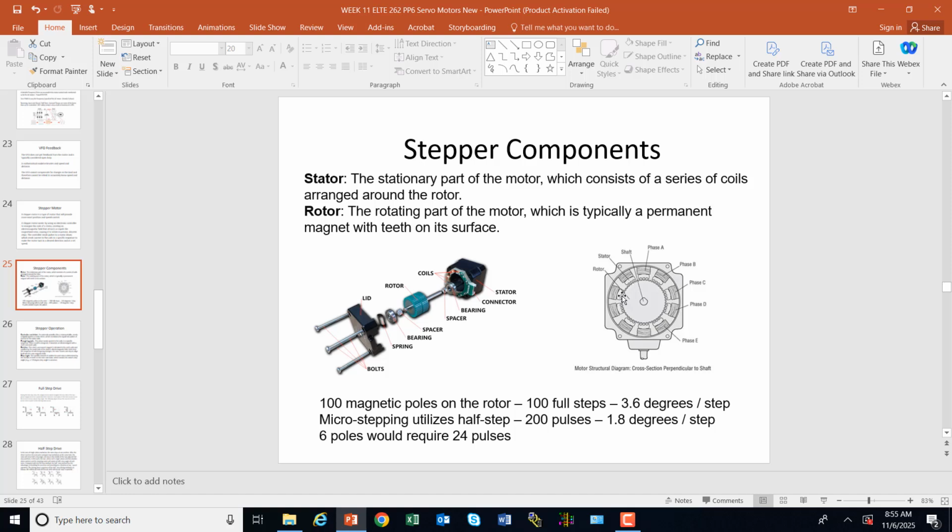And so these are going to be your steps, so that when you energize the coil, it is just going to click one step, okay? And it would stop. If you just pulse the voltage once, it would just click once and stop. It's not like all on or all off like an AC motor. And then you'd click it and it would move another step, and then another step, and then another step. So you know how many steps this actually rotated.